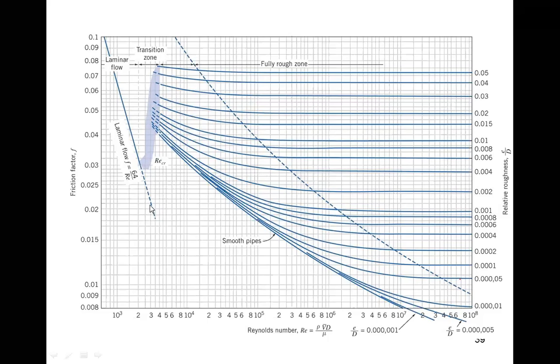And if you see this graph, the highest value of friction factor is 0.1. After that, the lowest value is nearly 0.03 something, or at the bottom end 0.008 in terms of RE. So as you increase the value of RE, your friction factor, or the losses due to friction, get minimized. So the highest losses are at low Reynolds number flow, in the case of laminar flow, and here the friction factor value is high in this particular zone.